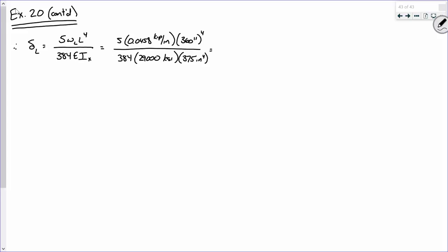That is an absolutely great, wonderful question. Why can you just compute the live load deflection, as opposed to concrete design? Well, yeah, but somebody kind of answered it. No cracking. Exactly. There's no change in I. Exactly.